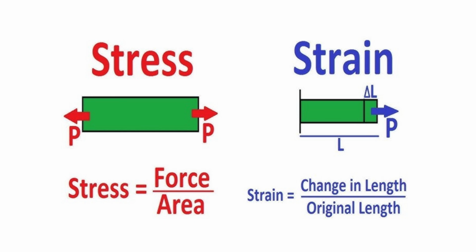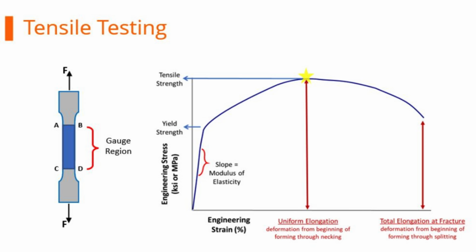Stress-strain diagrams are different for different materials. One can obtain the diagram for a specific material by performing a tensile test. This involves applying a known force to a test piece and measuring the stress and strain in the test piece as the applied force is increased. Perhaps the most important test of a material's mechanical response is the tensile test.